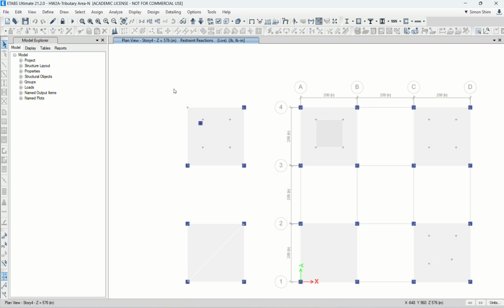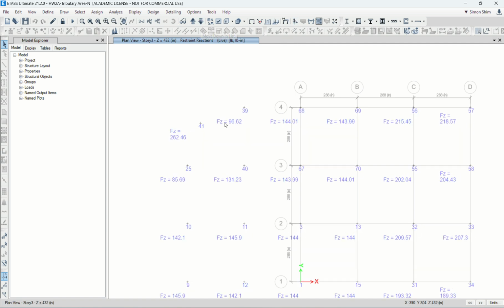Then let's see, based upon just the geometry and understanding. The sum of all this should be the same as the other model, because we have 24 by 24, and those are the total pounds we assigned: 1 PSF, pound per square foot, times 24 by 24.